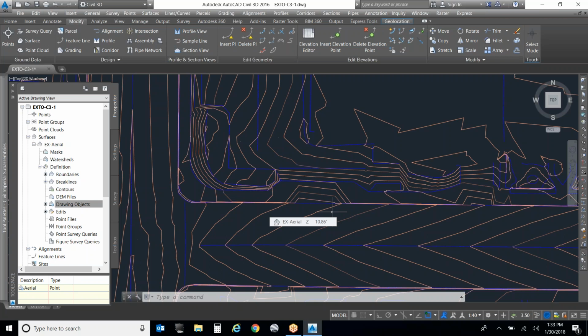Feather it out. So the issue is, like he's saying, if they go out with the GPS and pick up paint marks on the ground, survey manholes, and other stuff that's out there, surface utilities, is it worth it to add it to our existing topo? Not to add it, but to create a separate surface for it. So all that data would go in your EX-survey surface, and then it becomes a question of which surface you use as your profile.